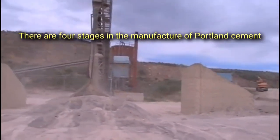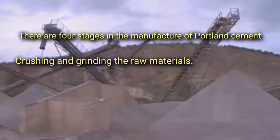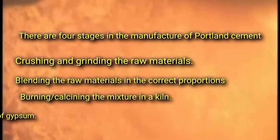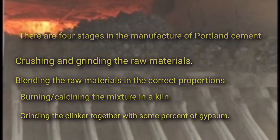There are 4 stages in the manufacture of Portland cement: crushing and grinding the raw materials, blending the raw materials in the correct proportions, burning, calcining the mixture in a kiln, and grinding the clinker together with some percentage of gypsum.